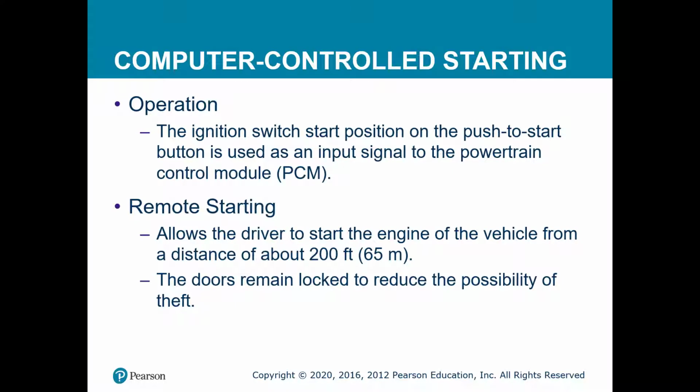Now, with regard to computer-controlled starting, which is essentially most vehicles now, as far as operation goes, the ignition switch start position or the push-to-start button is used as an input signal to the powertrain control module, the PCM. So essentially, it becomes a sensor, and the vehicle will not be allowed to start if A, your foot isn't on the brake, or B, your vehicle's shift select is not in park or neutral. There's a lot of criteria now going into vehicles, so they can't be started unless there's someone in it.